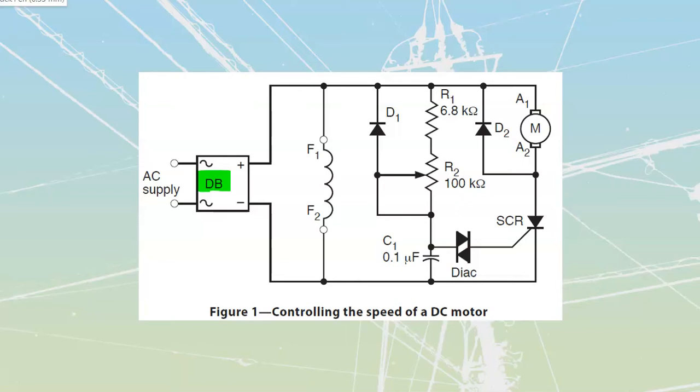You can hear these things referred to as, some people call them Wheatstone bridges. That's incorrect. A Wheatstone bridge is for resistance, but you're going to hear bridge or H type of control. And it's just going to be a full wave bridge rectifier, which means that my AC that comes into here, looking like that, is going to have all the bottom sections chopped off and flipped up. So we're going to get pulsating, full wave rectified AC.